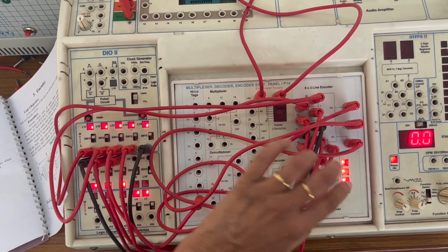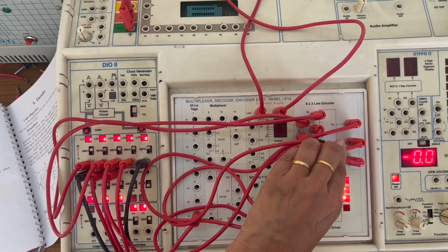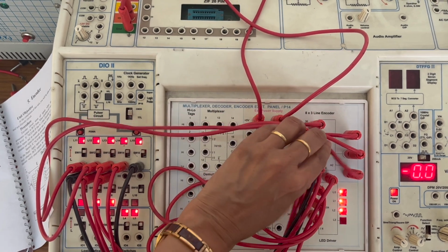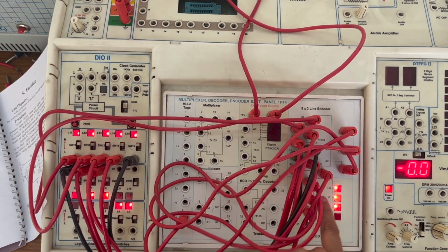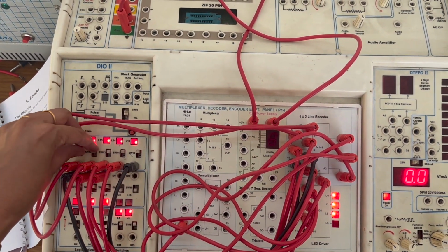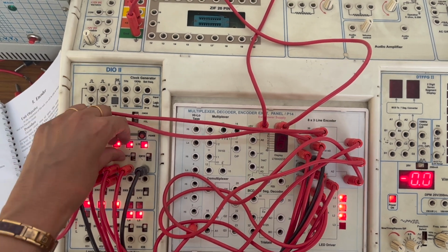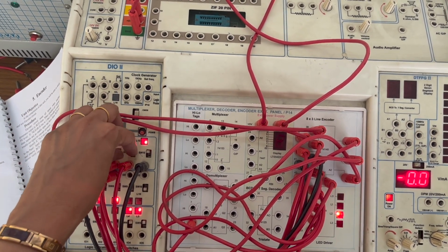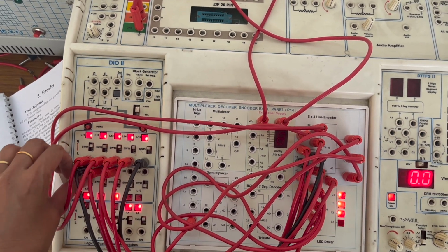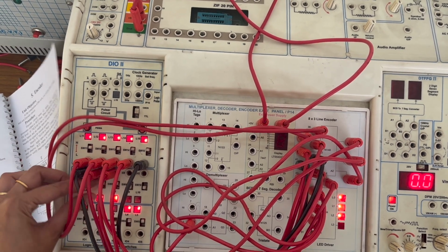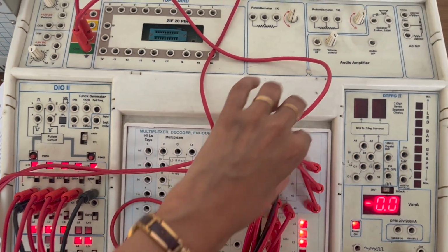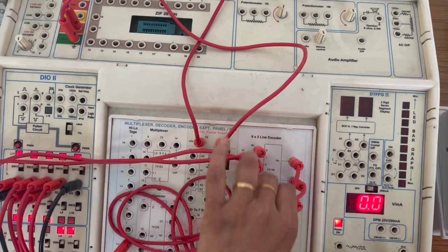Let's start again. This is 1 1 1. Actually it is 0 0 0 being complemented. It is displaying 1 1 1, right? So LEDs are going, right? This is 1 1 1. The second switch, first switch 1 1 1, second switch 1 1 0, third switch 1 0 1, 1 0 0, 0 1 1, 0 1 0, 0 0 1, and last switch is 0 0 0. So for one switch position change, we get one combination at the output. This is how this circuit works.